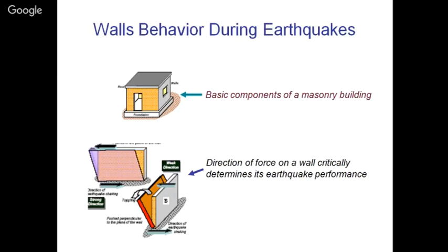As shown here, a wall is there in which the earthquake load is acting perpendicular to it. As we calculate the moment of inertia, BD cube by 12, the inertia will be maximum, and it increases if the earthquake force is in plane, acting parallel to the longer length of the wall.